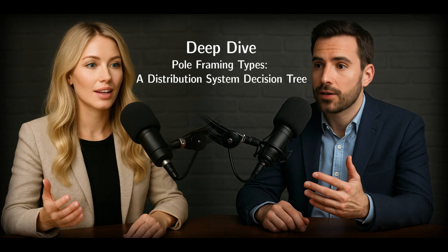Okay, the initial clue, the absolute first question to pose, is about the insulators. What type are holding the conductor? This isn't just a minor detail, it's the bedrock. Because different insulator types signal fundamentally different loading conditions. That immediately dictates the framing philosophy.